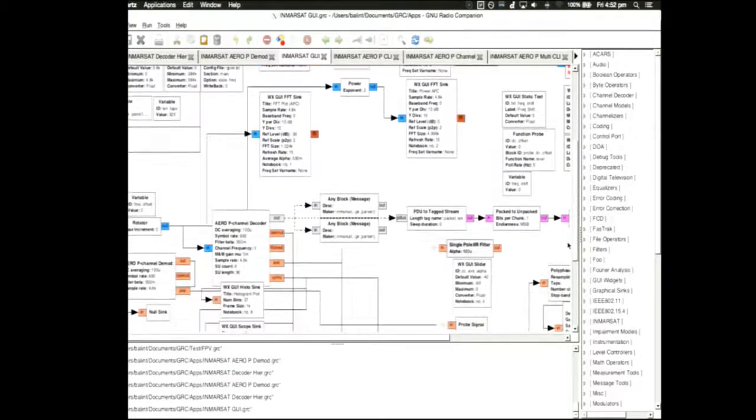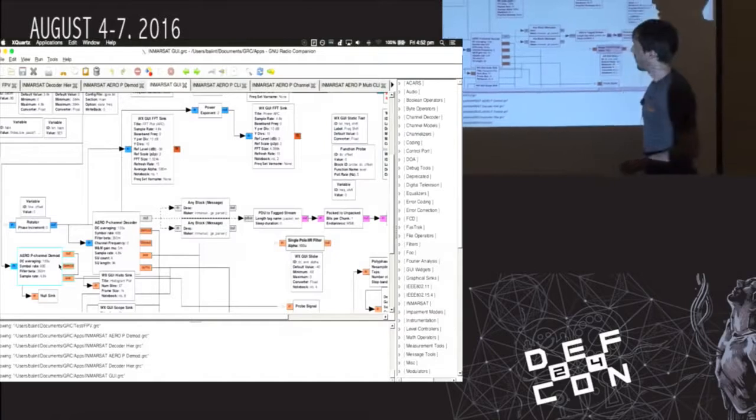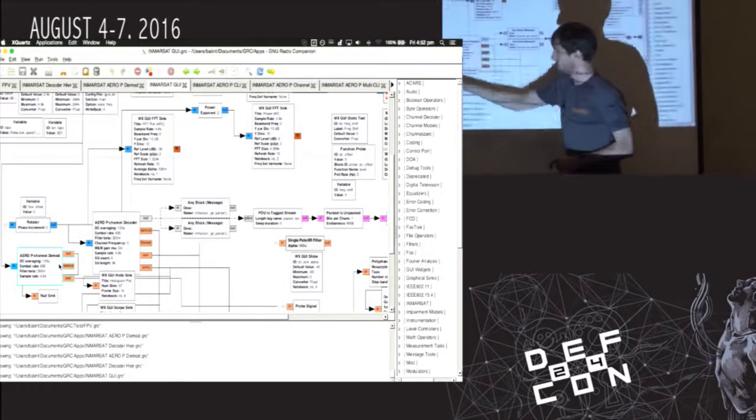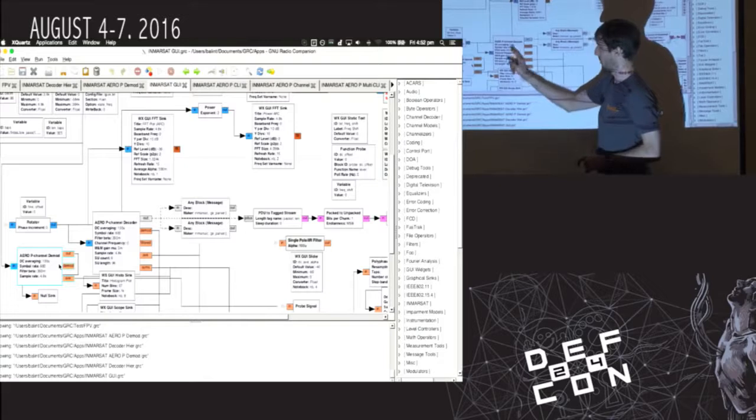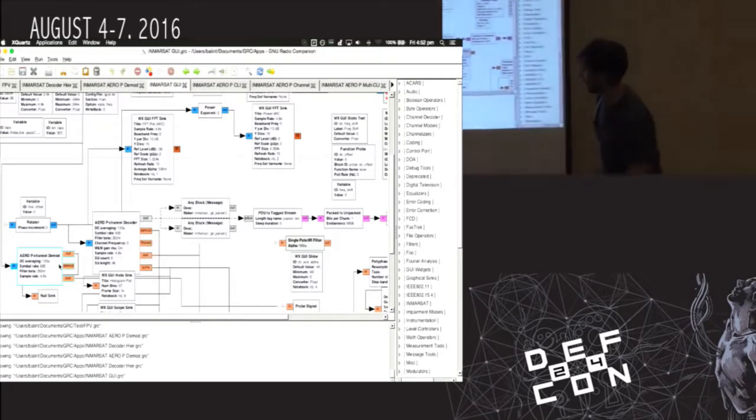And then there are a couple of different ways of doing this. But in this case, we go into the decoder here. And I've also got a demod here. And the reason why I have the demod is I'm not using the output. I'm just looking at the average value. So remember how the demod actually subtracted the average? We could actually just run it by itself. But because I want to visualize what the frequency offset is, and maybe plot it or what have you, I'm bringing this demod in here and just using the output of the average here. And then in this case, it's feeding back to the rotator, which is doing the frequency adjustment for that. Just another way to do it anyway.